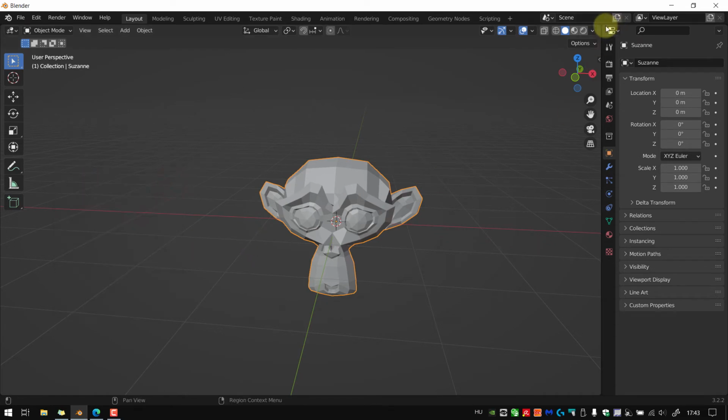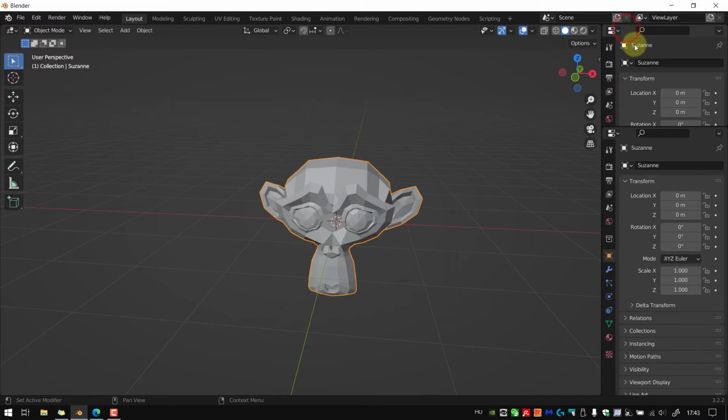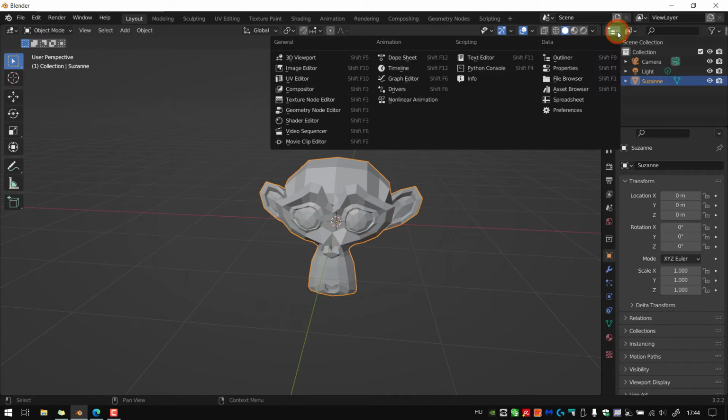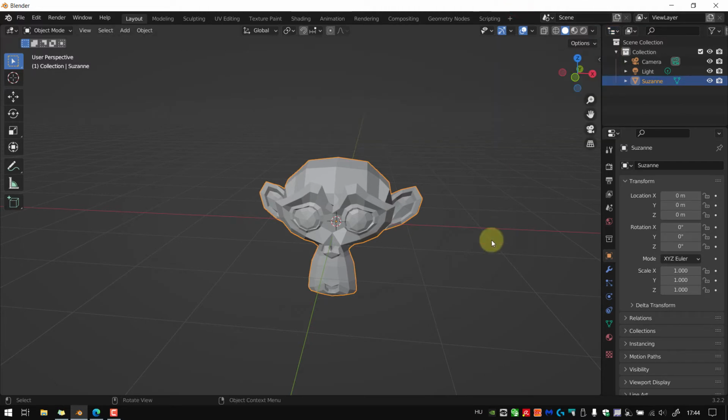But right away we don't worry about this, and I will just bring it back and make this active and press Shift Function key 9, and this is kind of the original way. If you forget about this, what corner, what not, you can always go to the divider and right click, and you have a vertical split, horizontal split, join, swap. So it works the same way, but don't forget, just go in here and pick the window you want to actually see, outliner, Shift F9. Okay, so there we go.